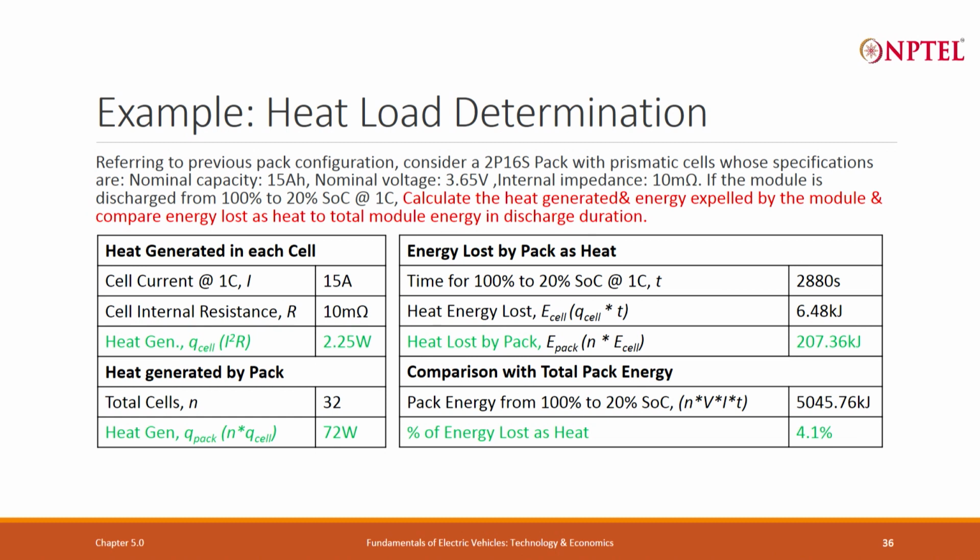If you are not taking out heat, that heat will get added up. So, the heat load is not only for the battery pack. If there is any heat coming from outside, or any heat going to outside, it will also be considered for the total heat load calculation, and then we have to remove that heat. If there is a temperature difference, it is impossible not to have a heat flow. You can reduce it by putting proper insulation material and all those things, but it cannot be zero. It can be reduced. We will talk about those things in a later part of the class.